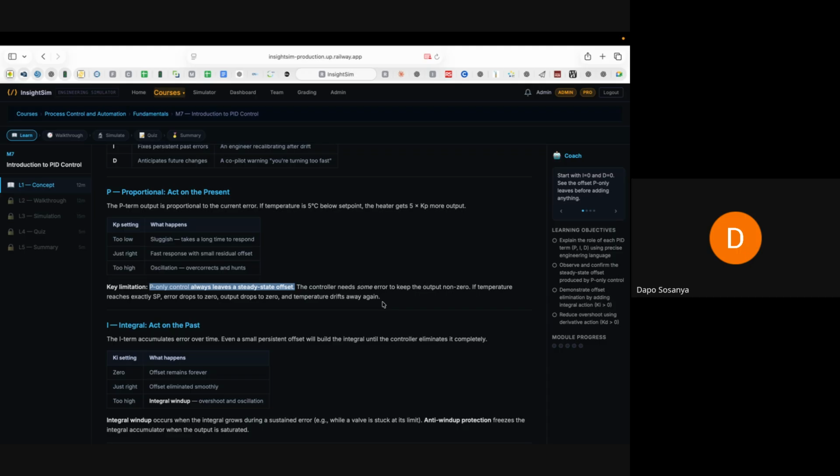But some processes, and this is where your genius is as a control systems engineer, some processes can accommodate what we call the steady state offset, right? I mean, it doesn't have a big effect on them. So they can accommodate a steady state offset, and you discover that they will be fine. So you don't need to implement a PI or PID algorithm for those ones.